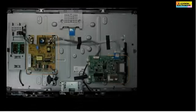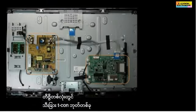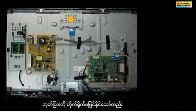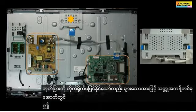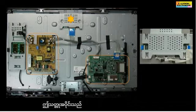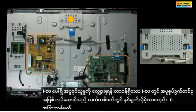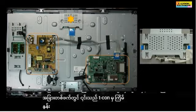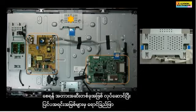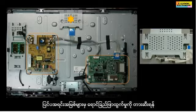Unlike the power supply board or motherboard, when a television has a separate T-Con board, it is usually not directly visible. The board is usually under a metal panel. This metal part has a double role. On the one hand, it serves as a heat sink shield that is responsible for reducing heat buildup on the T-Con. On the other hand, it acts as a barrier to prevent high-frequency noise from leaving the T-Con and to prevent the penetration of radiation from external sources.